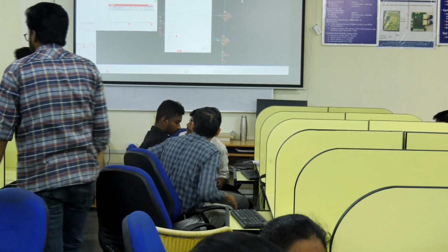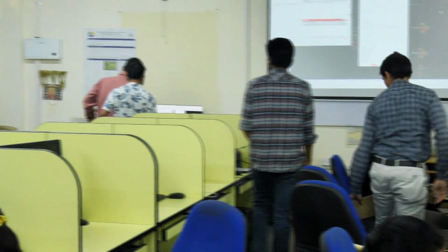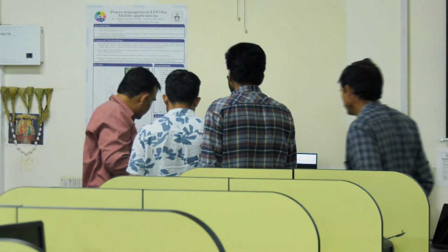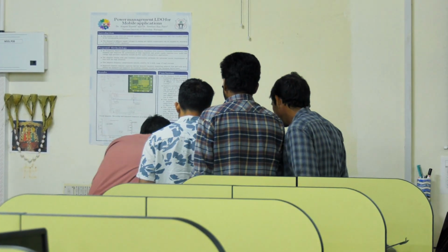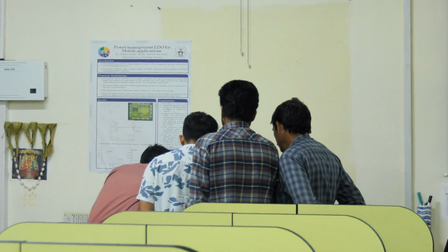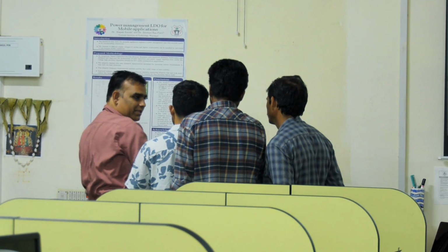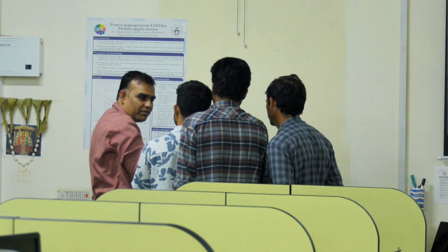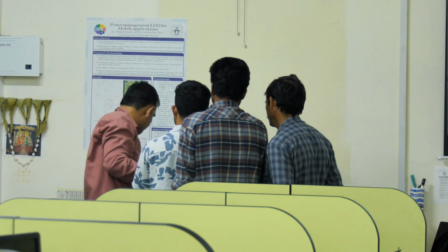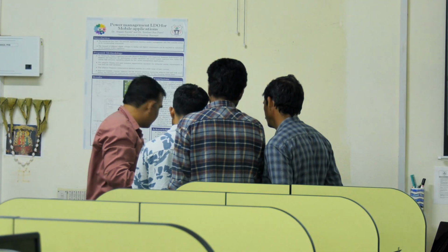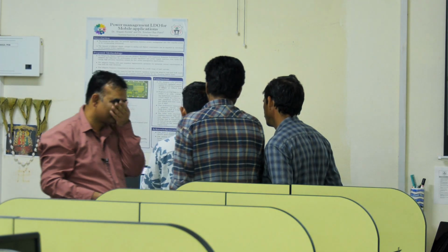So what we will do, so most chips have got a pad ring. You see this ring here? So this is called a pad ring. At the end of this, we have got these contact points. So we go and solder to these points, because the chip transistors are very small. We need to take them out as a big contact to connect to the rest of the world. So your array will go here. We'll connect the array to the pad ring, and out it goes.